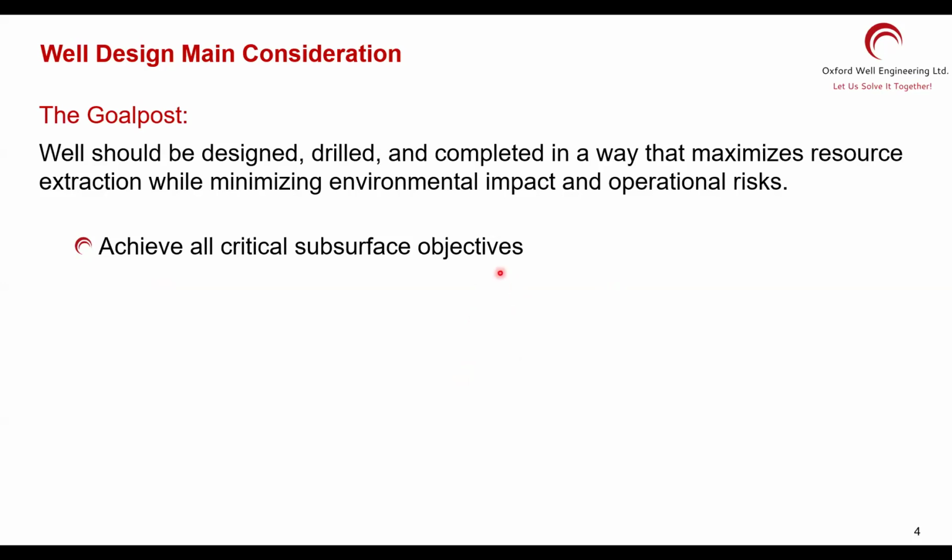What they definitely need is the most important thing that you need to focus on, because if you ask them, generally speaking, since the subsurface team are not drilling people, they may ask for things that will cost you a lot of money if you implement them. You can ask for flexibility. You can ask which ones are mandatory, which ones you can change just a little bit. For example, a target. They have given you a surface location. Maybe they don't have to give you the surface location. You give them the surface location. That is best for making the well cheaper.